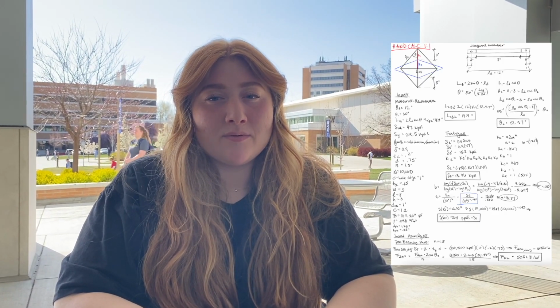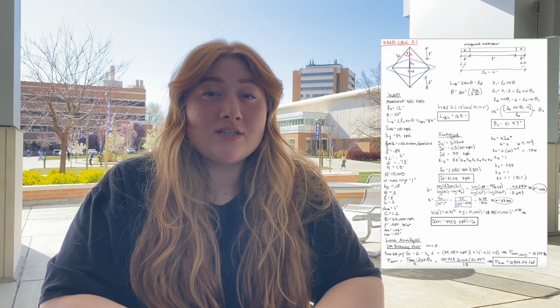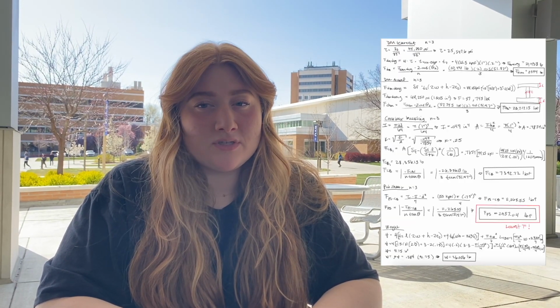Hand calculations are a necessary part of validating any model, as it ensures that the model is working based on both intuition and calculated equations. For our Scissor Jack model, we made preliminary calculations with arbitrary ballpark dimensions to calculate the maximum force and how the Scissor Jack failed. We then compared these values with the preliminary version of our code and ensured we got the same values as our hand calculations. This is extremely helpful as we found small errors in our code, such as a missing negative sign or the wrong dimension used. We did hand calculations for 2 different materials to make sure both matched the code, and even made sure the code matched our preliminary hand calculations we did in a homework assignment for the Scissor Jack.